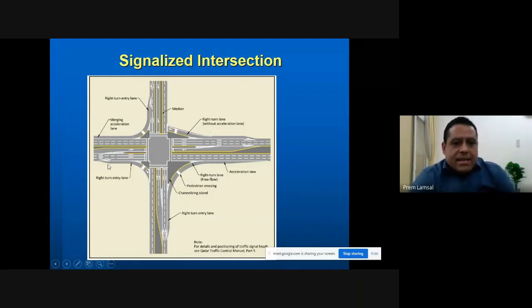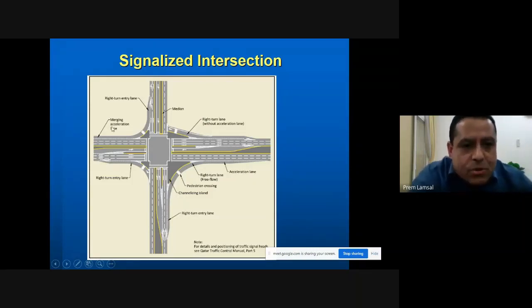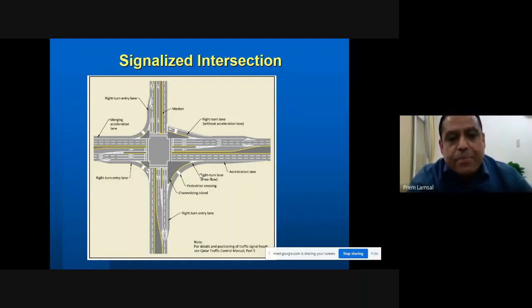And again, you can see here, whenever a vehicle is coming from this road, hope you are seeing my mouse. When a vehicle is approaching here, this is the turning movement here. Whether to put this island here or not, whether we need to design this, how many lanes we need to have in between, what should be the length of this storage length, and what should be the length of acceleration and deceleration lanes. These all depend on the design speed, the turning movements, and traffic volumes.